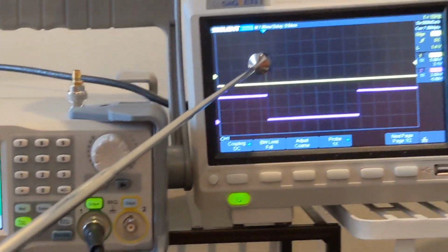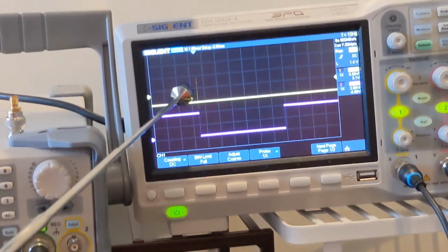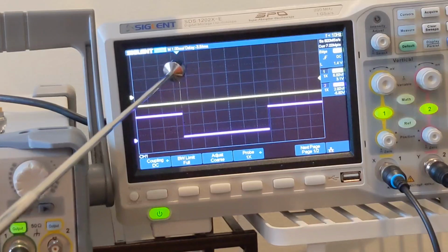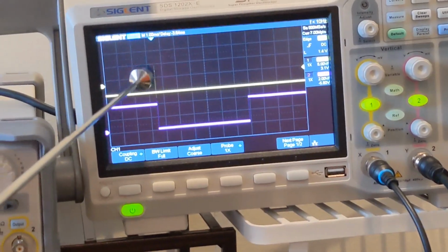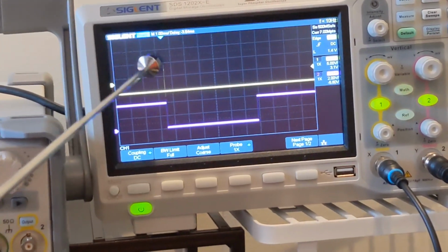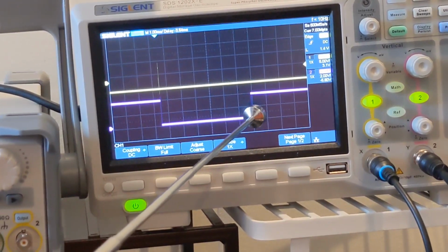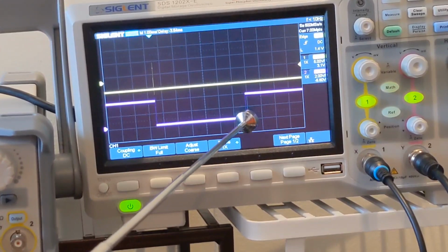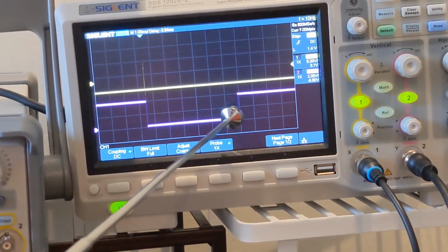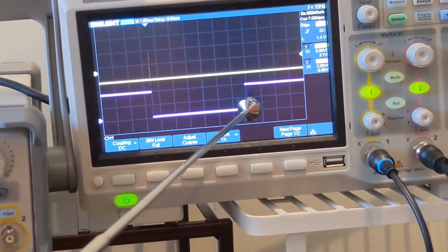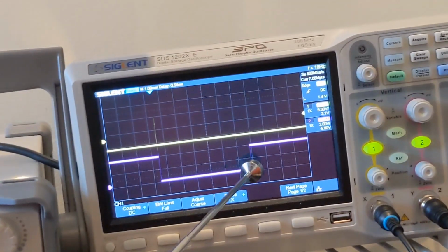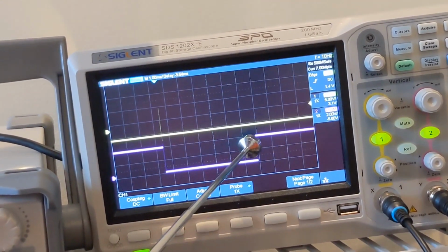Once we get here, we see the 1 microsecond kind of show here. It's difficult to see, but it is there. And then that triggers a pulse that is already almost 6 milliseconds. That 6 milliseconds is easy to see with a microcontroller or even with a laptop, with a computer. So that's what you want.